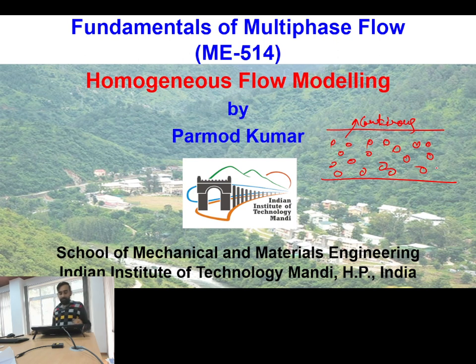But as an engineer, my interest is only to make my system work. I am not interested in minute details of what is happening within the pipe, but my overall goal is, say, to transfer some slurry from one location to a location 5 meters downstream or 5 kilometers downstream. In a 5 kilometer long pipeline, my major interest is what should be my flow rate, and with that required flow rate, my particles should not settle down and should not block the pipeline. So based on that, I will decide the velocity of the continuous fluid and the size of the particles, so that these remain suspended in the fluid.